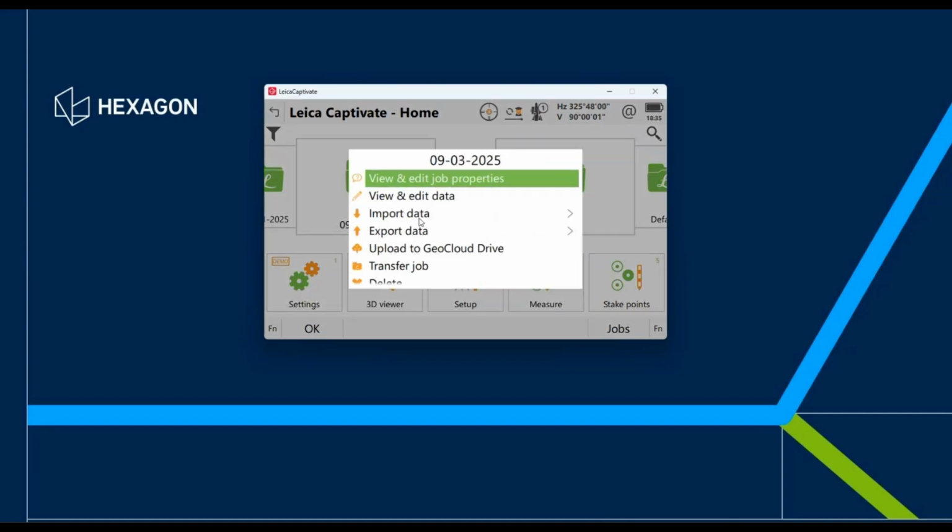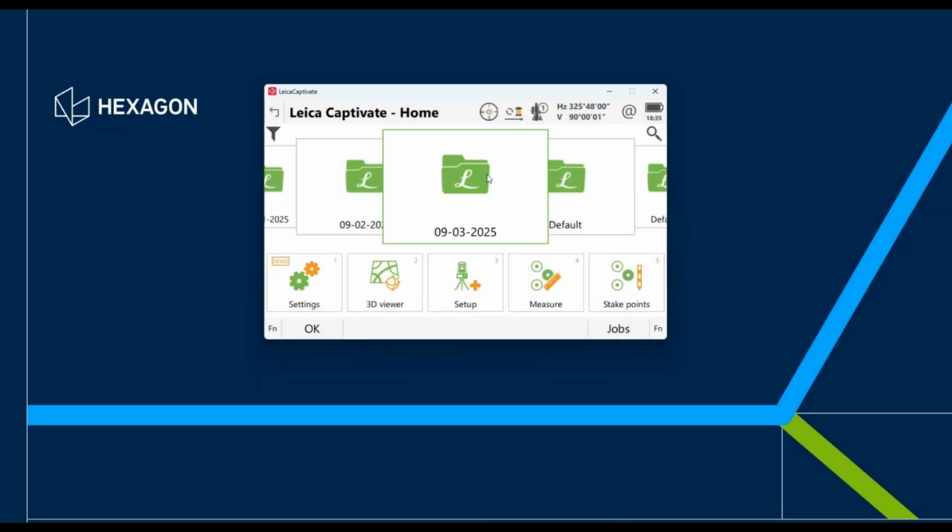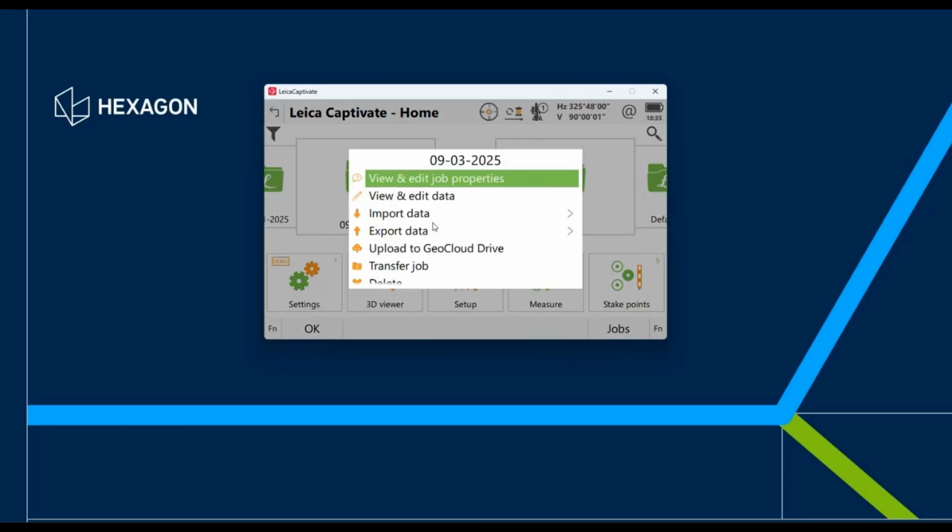Finally, if I want to import a text file, so I flip my job, import. A side note, most of you might be aware, but there's also an option to import a DXF file. And you don't want to use that option. When you do that, it will import points and lines from the DXF and import those points and lines within your job. So it's not a reference file anymore, and it will populate your job with hundreds of points and lines automatically. So if it was just from me, I would remove that import DXF.